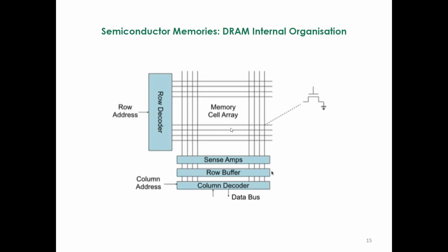Okay, so basically, with the rows and columns configuration, if you want to read from a specific address, you have to select the row, and then depending on the size of your memory, that entire row could be 32 bits or it could be 64 bits. Then you might want to only read a byte within that 32 bits. So you select those using the column decoders, okay, the column decoders.